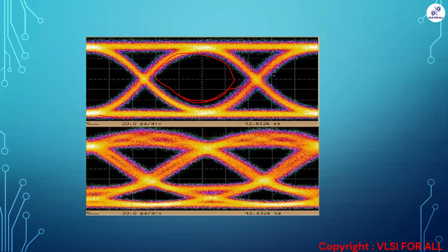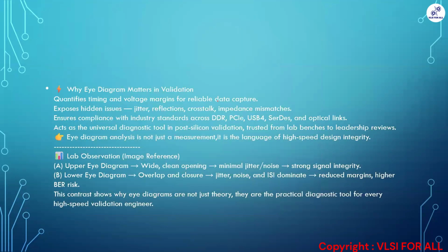And this vertical length is also good, which means the noise margin is good and noise is less. Vertically it also has more width, which means the ISI effect is not much on this eye diagram. So by doing this type of analysis for high speed IPs like SGMII, Aurora, PCI, USB, DDR, for that type of IPs we will do signal analysis like that.